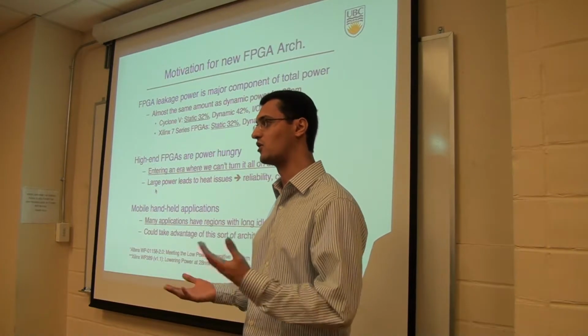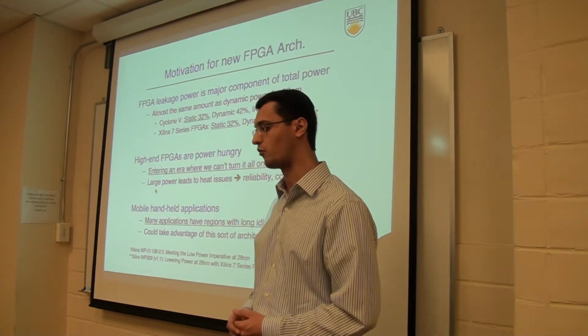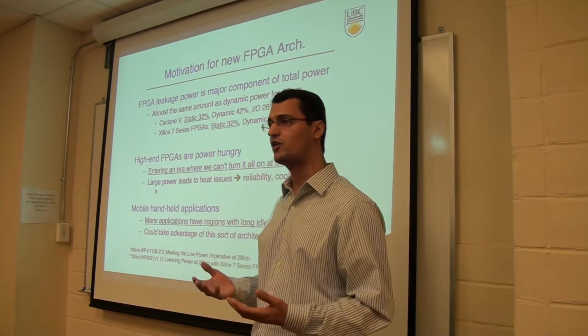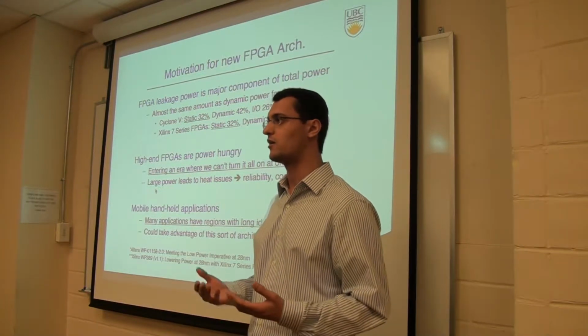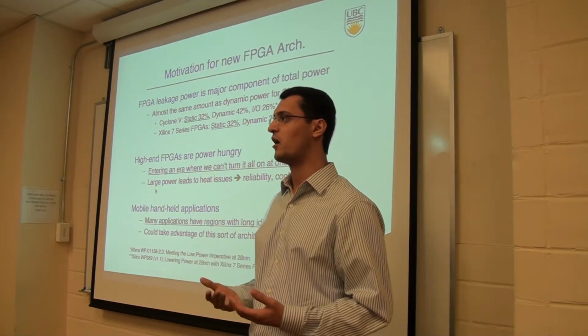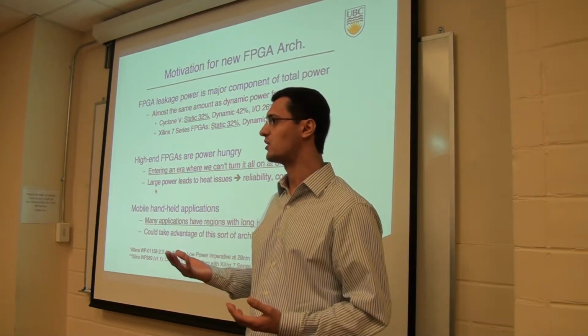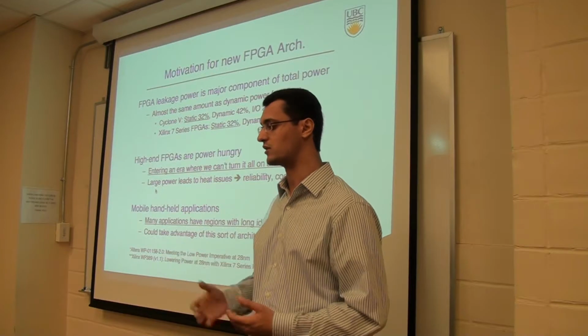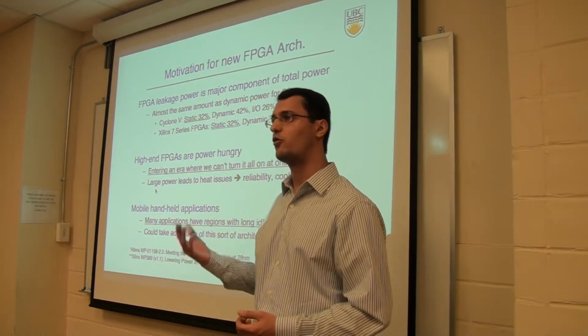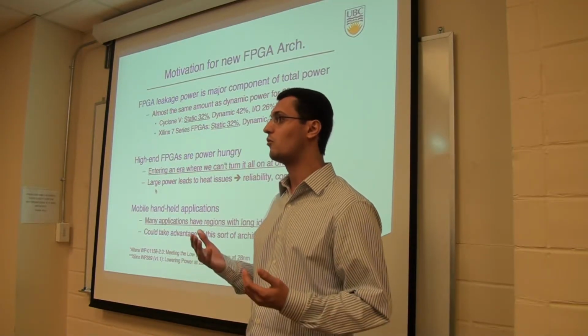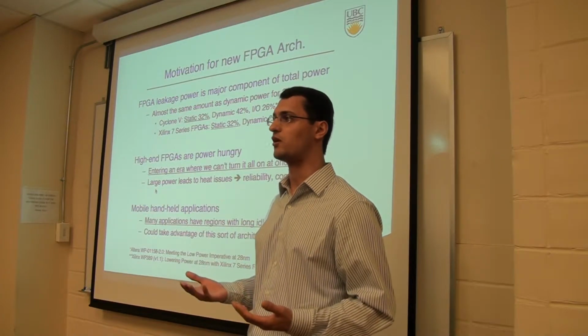Static power and dynamic power are both becoming major components. In high-end FPGAs, each year they become more dense, with millions of cells inside them, and we are approaching a point where maybe we cannot turn on the whole FPGA at the same time.